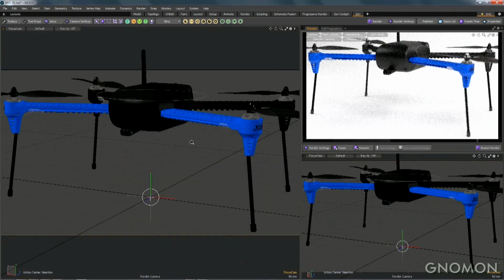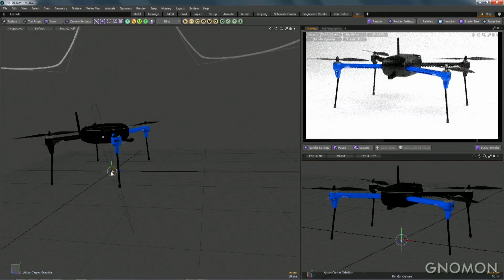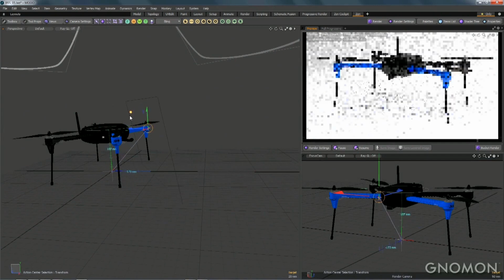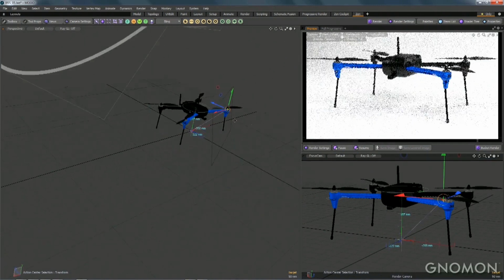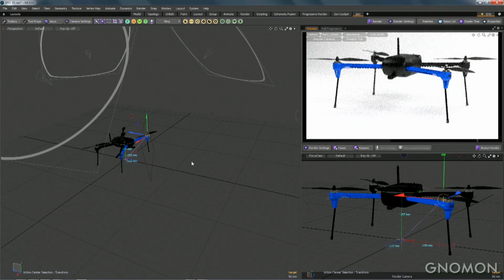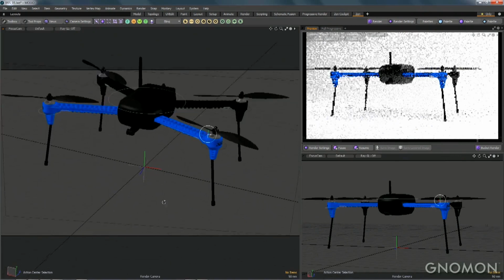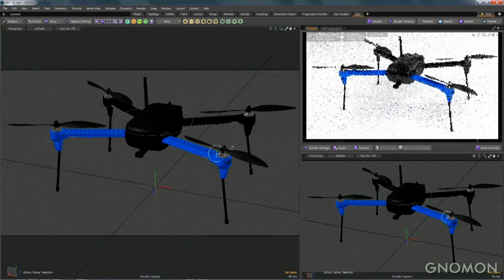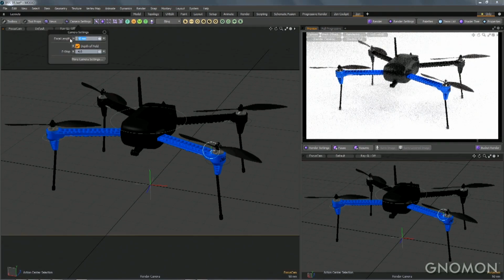Now, the thing about this camera is that it actually gives us a locator item. There's a circular locator in the center there. And as I move that, you'll notice that the gray focal plane is moving along with it. So we get a preview of the focal plane and the crop with the current camera, as well as a static focus location. So as the camera moves, even if it's animated, it's going to stay focused on the right place in my scene without doing any extra work.